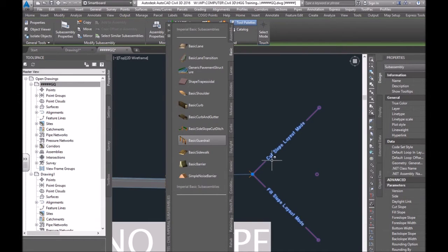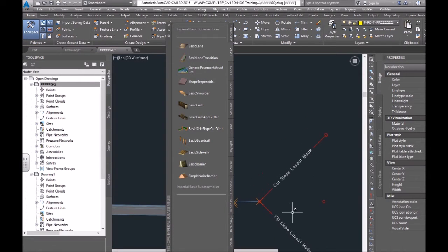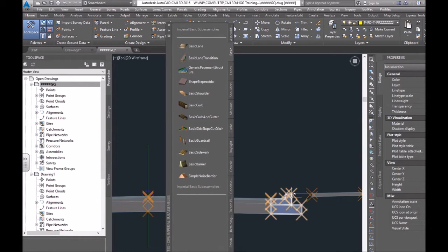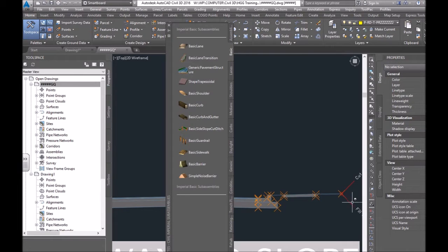Like I said, this is under basic. And like I said, there's a whole bunch of different options here. And we might get to these as we're going through the corridor models. Corridor models can get pretty complicated depending on how you do it. Like just modeling some things like extruded curb, depending on how you're doing it, might not be worth it to model it with just an urban curb gutter. You might need to use your own curb. So there's also like basic curb, but generally these 4 should be what you need.